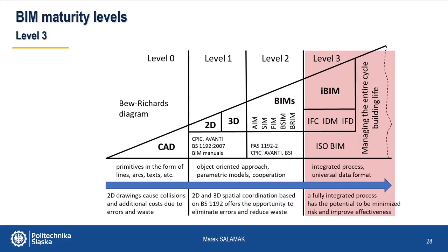The last phase, level 3, is one common project model available to all participants of the investment process directly and in real time, with scheduling, BIM 4D, bills of quantities and cost estimates, BIM 5D, energy analysis, BIM 6D, and information about the facilities, about the assets in the life cycle, that's 7D.